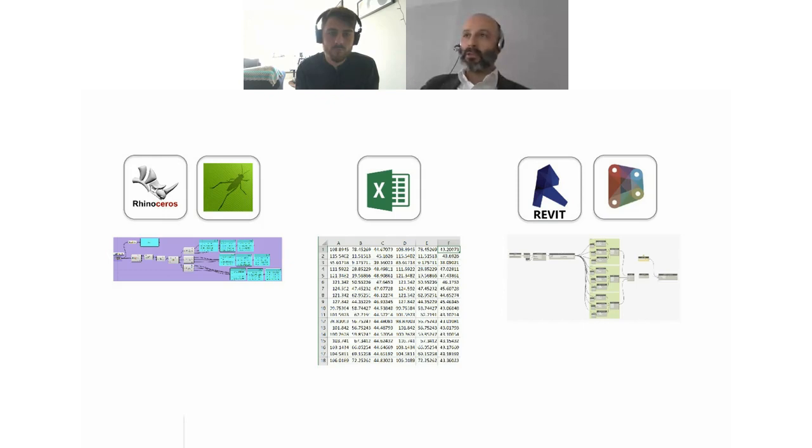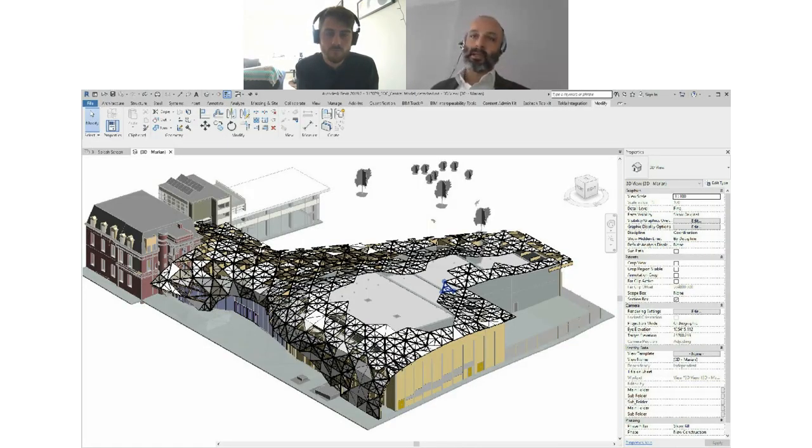So the actual solution required only 2 very short scripts, one in Grasshopper to export a list of corner points to Excel, and another one in Dynamo to import that data and generate the panels with a smart adaptive component. Therefore these 600 unique panels and their associated subframing could all be modeled in less than 2 minutes.